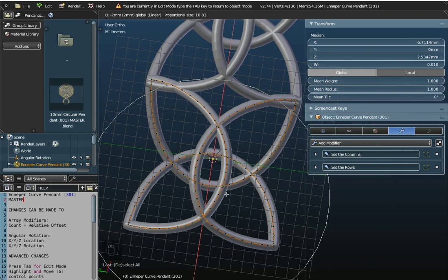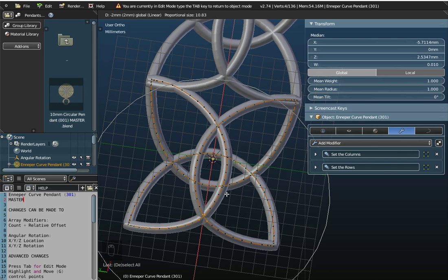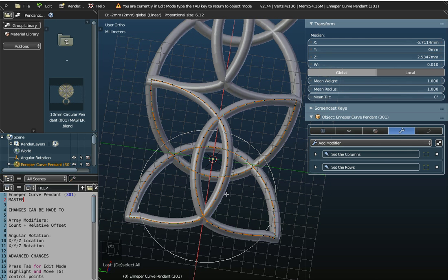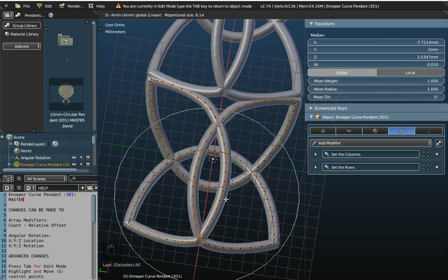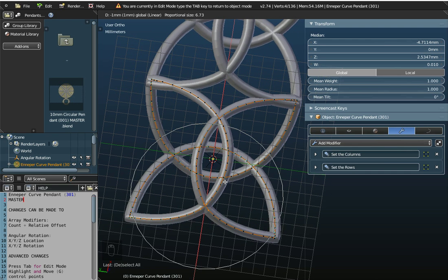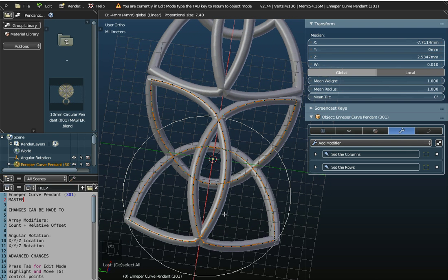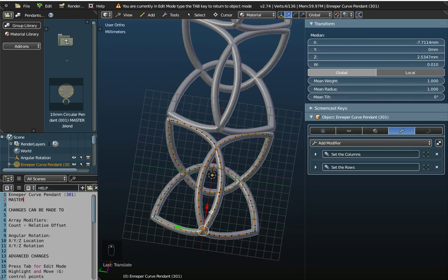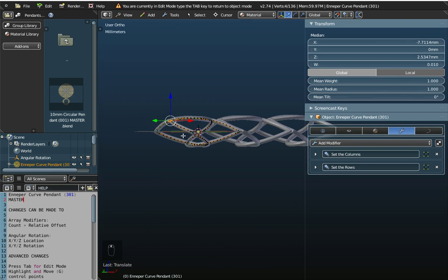Now at the moment I've got proportional editing on, that's this big circle here. Now I can close that circle down by scrolling the center mouse button. I've still got my finger on the left mouse button so that I can modify this object, but I'm adjusting the proportional editing circle by scrolling the center mouse. So I could modify my pattern. So it's modified it on this object, but it's duplicated on the other 3 objects as well.